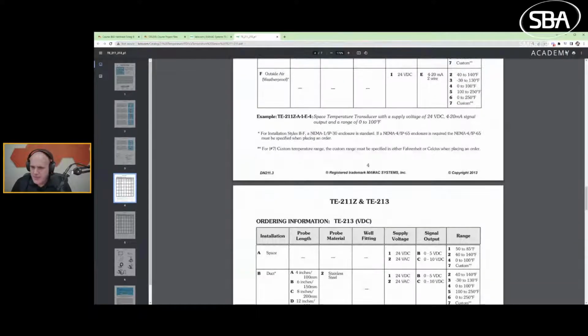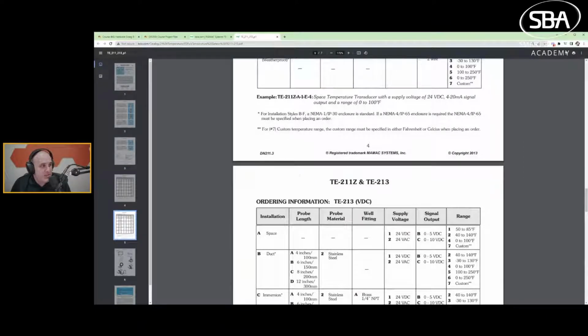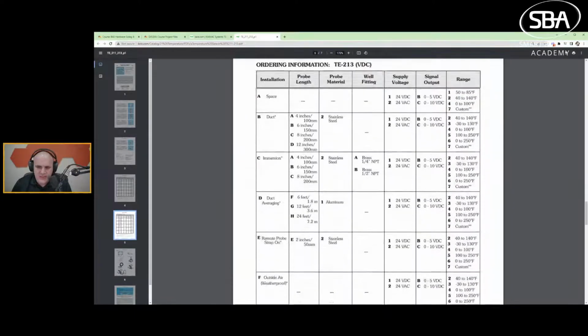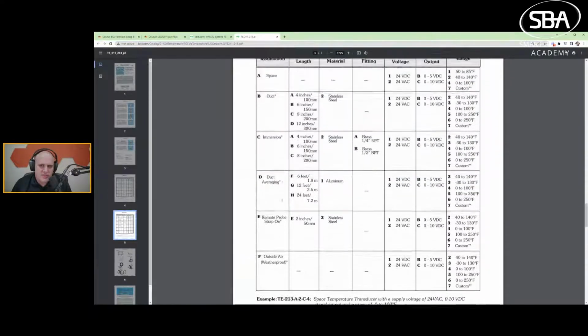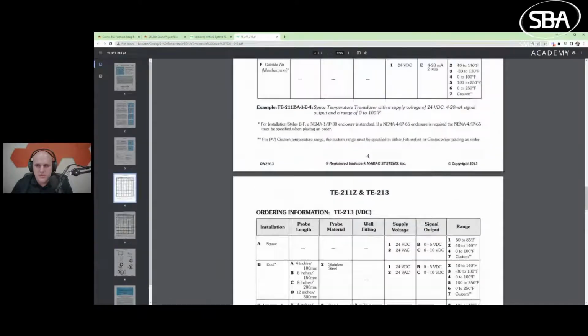It doesn't tell me what the element type is, so I'll have to figure that out. That may be something that I have to send in an RFI or a call to whoever is the manufacturer of this. But I know this seems super difficult, and once you've done this a handful of times, you'll start to build up your list of materials, and this should not take you very long at all. Because the nice thing about building automation is pretty much every sensor or device IO that you could think of has already been used in most projects. So it's not going to be terribly difficult.